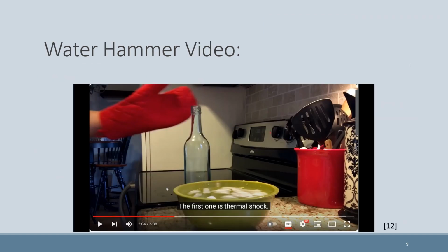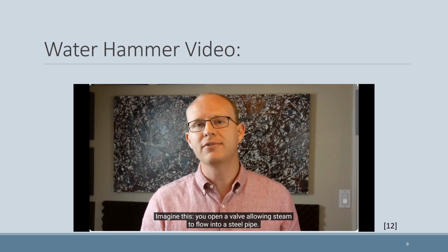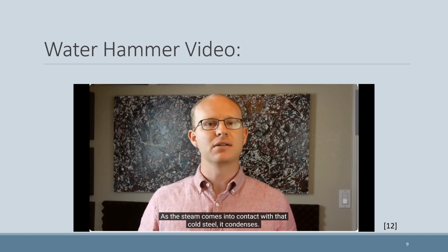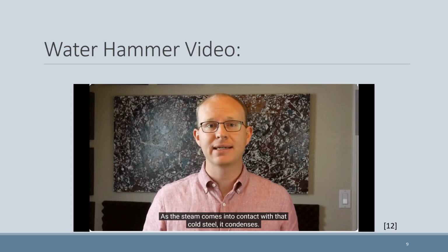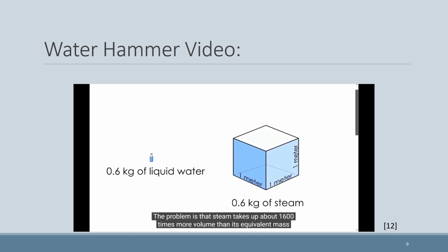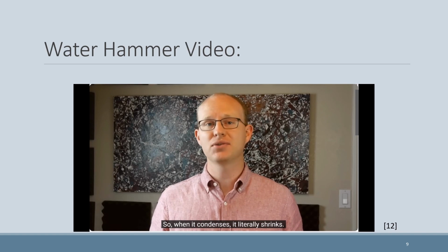This video will help explain how important proper maintenance is and how dangerous water hammer can be in a steam line without the application of steam traps. Imagine this. You open a valve allowing steam to flow into a steel pipe. As the steam comes into contact with that cold steel, it condenses. The problem is that steam takes up about 1,600 times more volume than its equivalent mass as a liquid. So when it condenses, it literally shrinks.